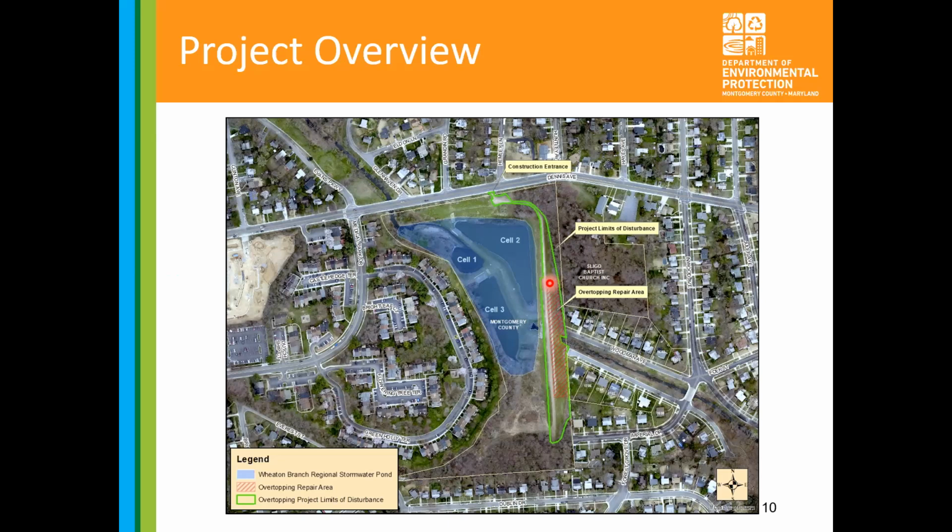The spillway was protected by gabions at the top. You probably noticed some cages with concrete. They look like concrete, but they are really gabion baskets with stone, and they were grouted.